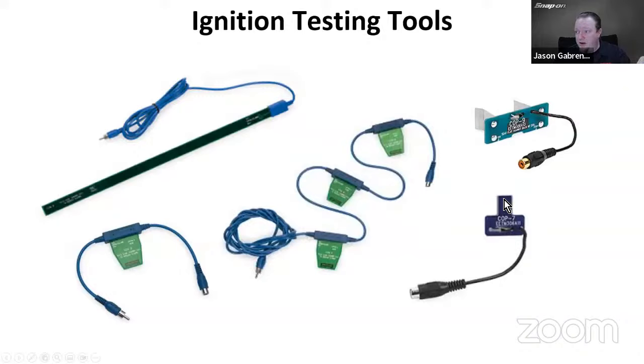There are also various coil on plug specific adapters for different types of ignition systems. There's one for HEI. There's one for the older Honda coiling cap. And then there are various different adapters. Here's one I have sitting in front of me. It's a COP3, right? That's got the RCA plug on it as well. They're made to fit individual coils or certain types of coils. There is another one that we have called the COP11. We just redesigned it, and that's kind of universal.